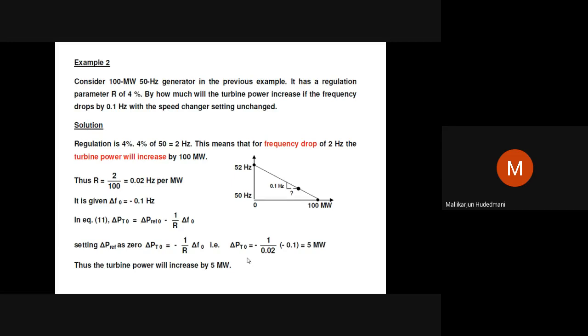Here, the turbine droop nature of 4% will adjust the fuel so that the turbine is going to shift its output for every drop of frequency in the line. How much power deficit is noticed, because of which the drop in frequency in the system is observed, is to be understood.